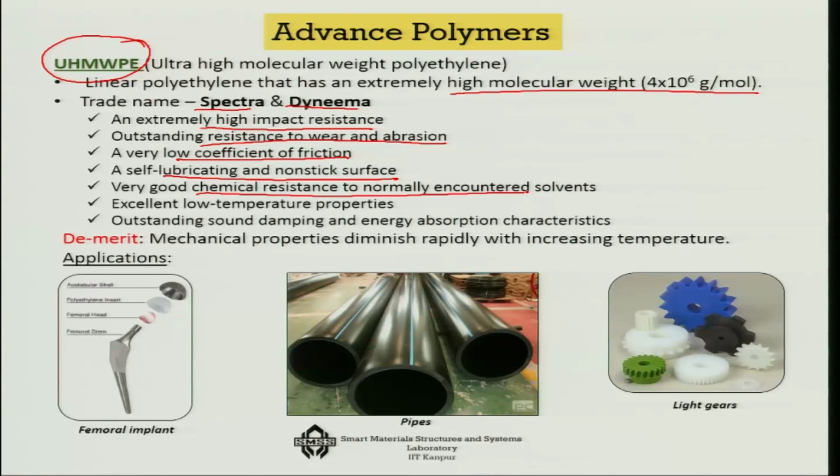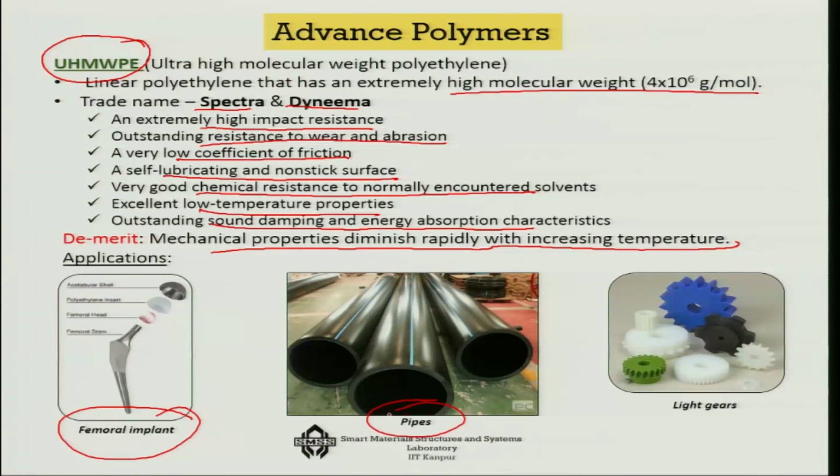They have very good chemical resistance to normally encountered solvents, excellent low temperature properties, and outstanding sound damping and energy absorption characteristics. The only thing is that their mechanical properties diminish rapidly with increasing temperature, because they are linear polymers. So they are susceptible to, as I told you, creep like problems. But if the temperature change is not very high, then they have excellent properties. They are used in femoral implants, pipes, light gears in Legos, etc. That is one example of advanced polymers.